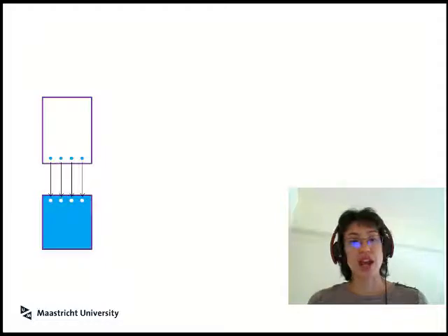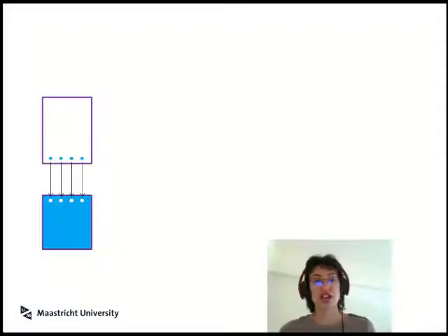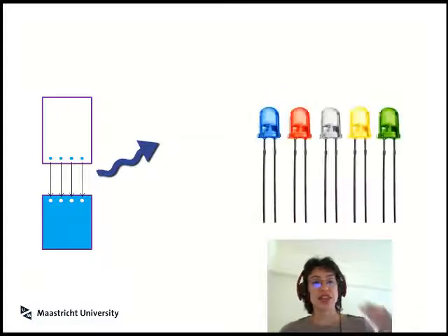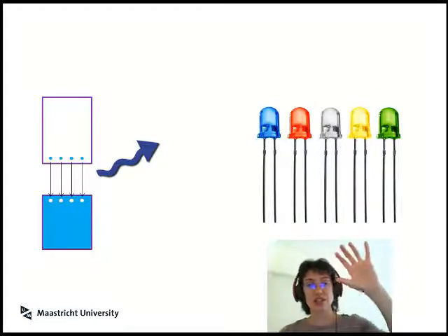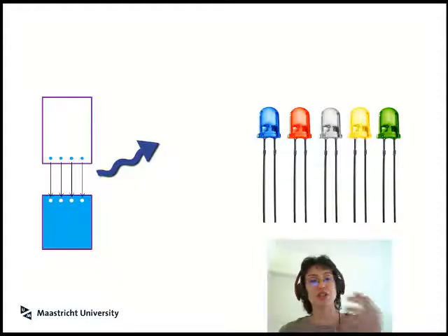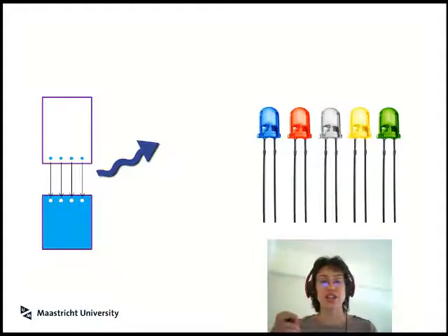This is the same way that LEDs also give out light, but it's the reverse process. So in an LED, you get light given off as electrons that are already excited into the conduction band drop down into the valence band, and they give off light at very specific frequencies, and that determines what color your LED is. So it's actually the semiconducting material inside your LED that determines the color and the frequency of the light that's given off.